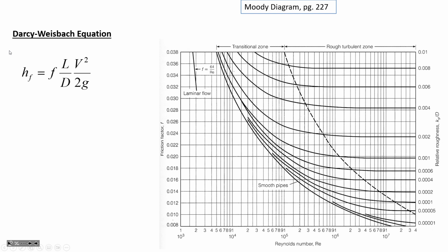The pressure head plus the elevation head plus the velocity head plus, if there is a pump, H sub P, is on the left-hand side of the equation, is equal to, for the right-hand side of the equation, the pressure head, elevation head, velocity head at 2, plus the head loss due to pipe friction, plus the head loss due to local losses. And collectively, we sometimes combine these together and say that they are the head losses.